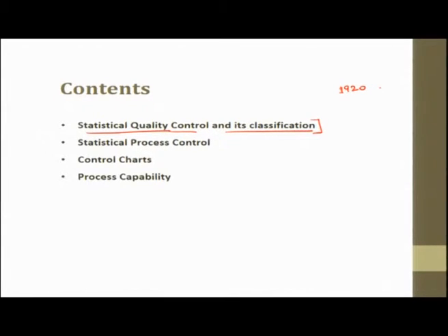The department is generally known as inspection and quality control department. If you see the books or find the topic, you will find it as inspection and quality control. Inspection is when we just check the specifications, like we use comparators or some measurements and we say okay, yes or no, go or no go, acceptable, not acceptable, that is just inspection. But when we plot the results obtained from inspection and try to see where the flaw lies, if our manufacturing process is not within the control limits, that is statistical quality control. I would like to say it is an extended version of inspection. However, we will not go off on that tangent, but will focus more on quality control.